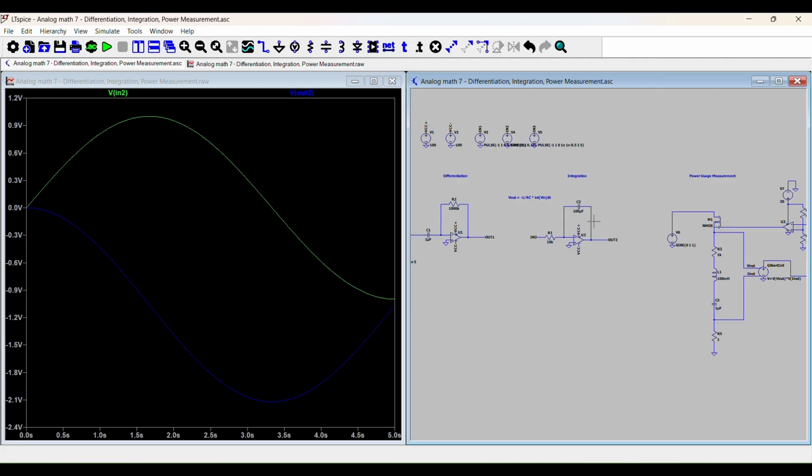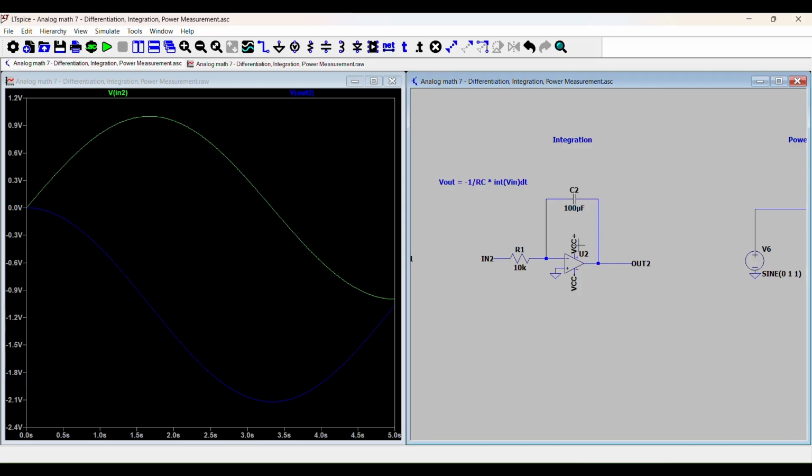Another thing to note is what's actually happening in the circuit. We know the mathematics works out, but what's actually happening is this circuit is feeding in a current, because this end's tied at 0 volts. The input's not a constant current, it's a voltage-controlled current source here. So it's basically the voltage divided by 10K. That's the current across here.